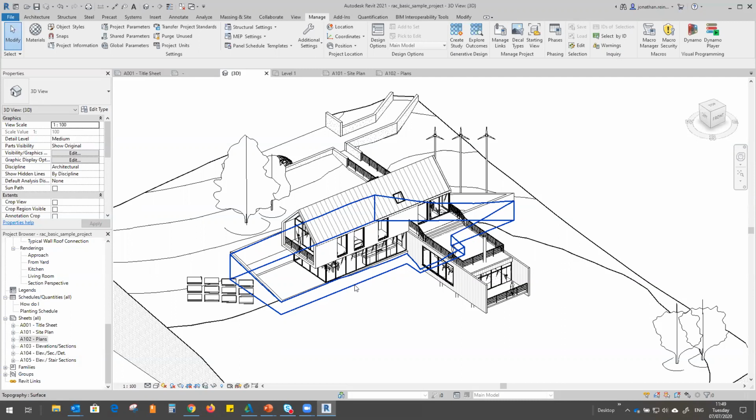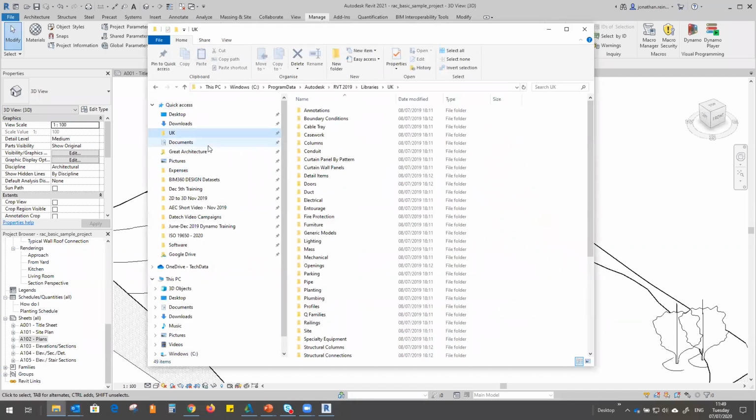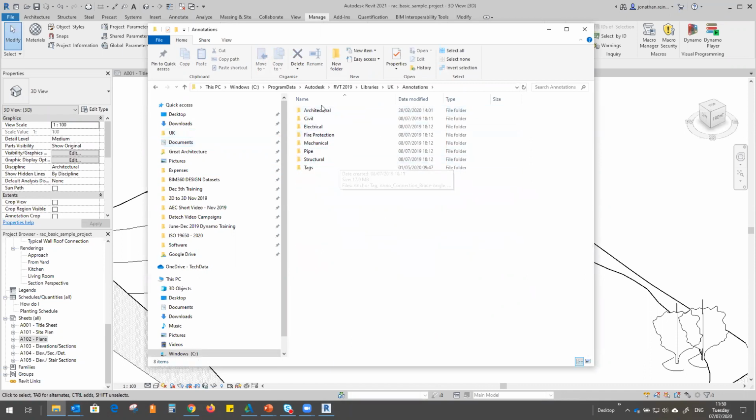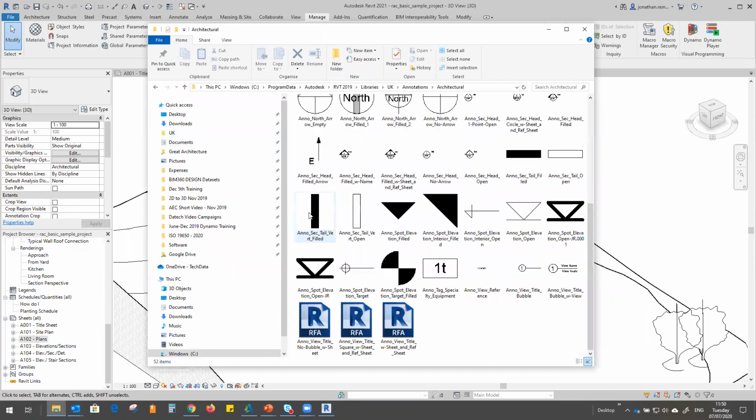In the sheet view, can the font size be changed? It can, yes, and that's the same way you control your grid bubbles as well. A lot of these questions will come back to setting up your company template, where you'll create one project and you'll have all of your standard text size, dimension size, and all those styles. You can save that as your company template and then reuse it, and that goes for grid bubbles and even text size as well.